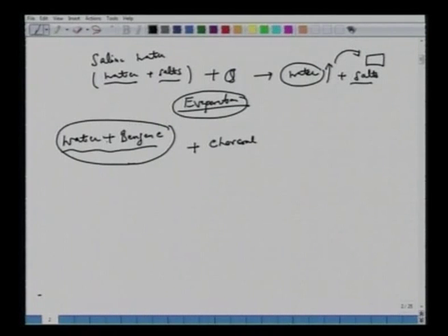So benzene contains some amount of moisture, and now we want to remove the moisture from benzene, so we bring it in contact with charcoal. This is also not drying. Here we are talking of multi-component adsorption. So this would be adsorption, although we are removing moisture from benzene. Alright, so in different operations we remove water, but it's not necessarily drying.